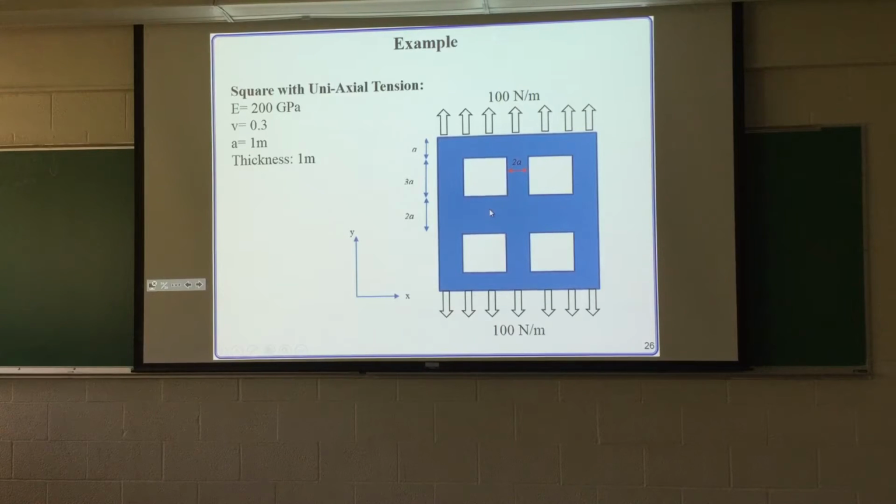Also, one thing to note about this image, we don't have any fillets on the inside squares. And as we discussed in class already, if we were to run the simulation, we would never get the stress to converge, as in if we increase the mesh size, the stress concentration is just going to keep increasing and we're never going to get a constant stress, and we're just going to keep increasing the stress value. So we're going to go ahead and go into Abaqus and draw the part.